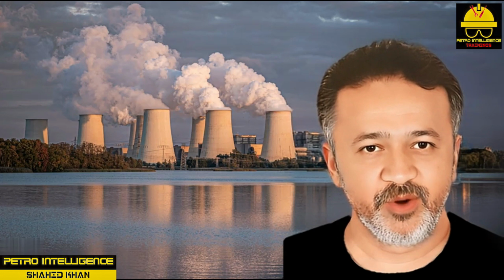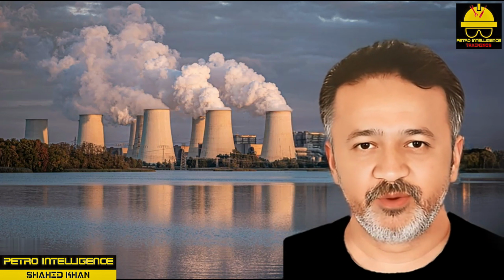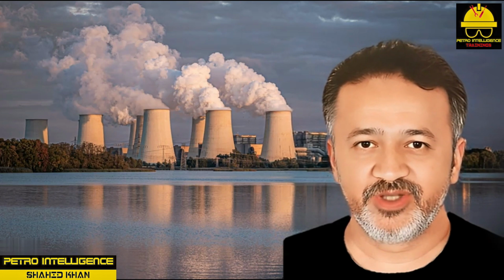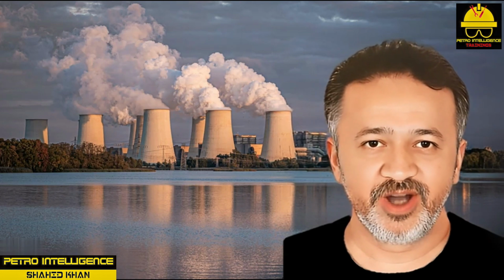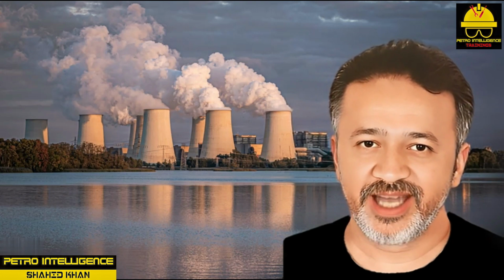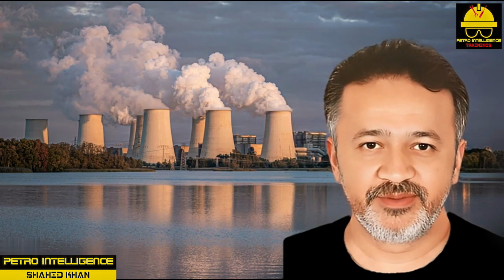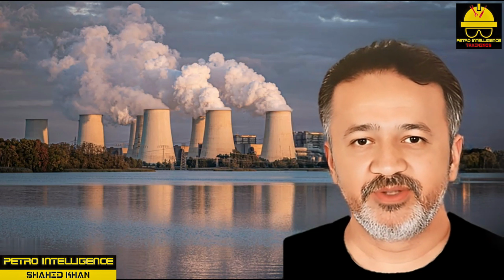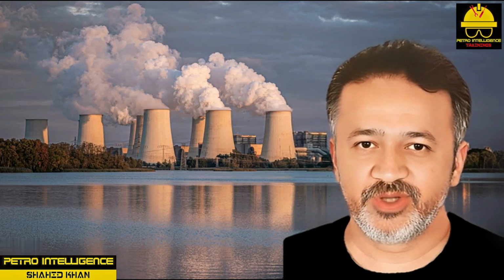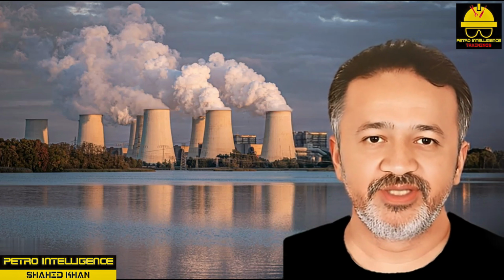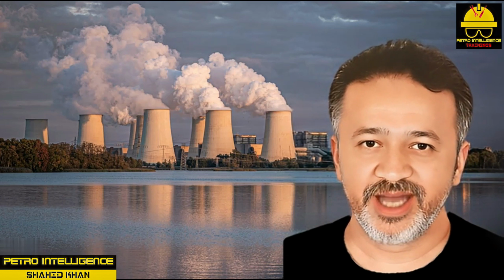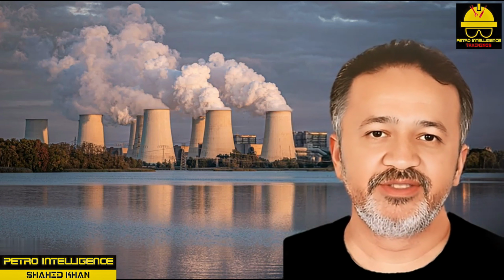The trouble with water. Over time, water dissolves everything it touches. The Grand Canyon is strong evidence that water can remove large and small obstacles. Hot water dissolves solids faster than cold water. Hot water dissolves a little bit of everything it comes into contact with. By the time the hot water returns to the tower, it is full of suspended solids. Hot water also has a tendency to become corrosive and to form deposits.